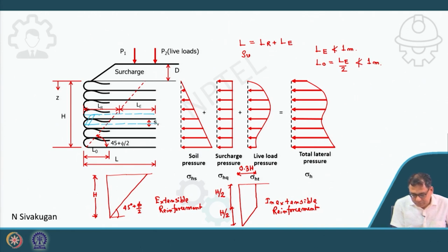So, if I take this small segment between the middle of these reinforcement layers, the spacing between two reinforcement layers is SB, and so definitely the thickness of this small segment that we have taken is also SB, because this line is taken in the middle between these two reinforcement layers. So, this is SB. Clear?